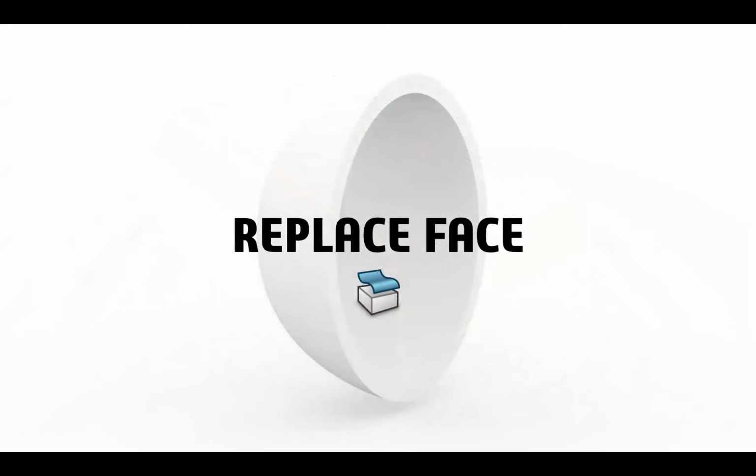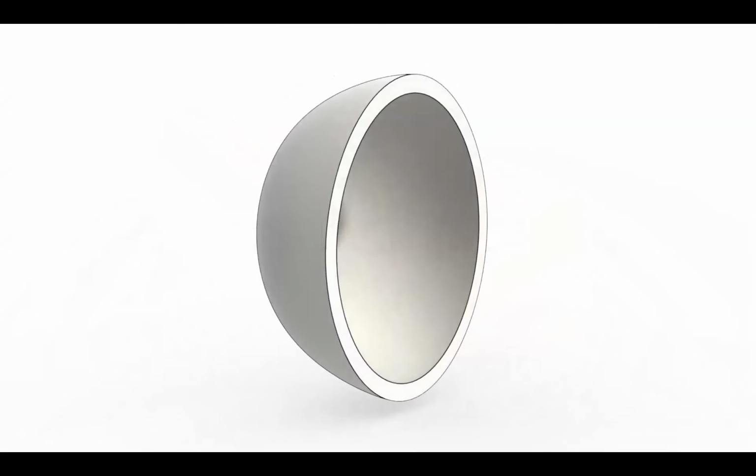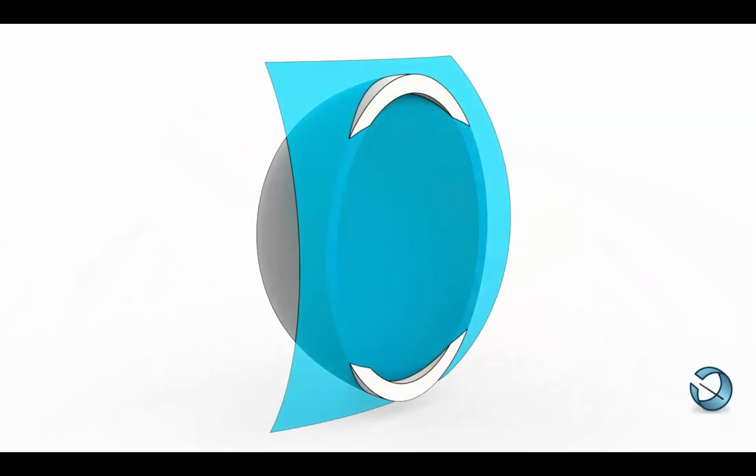Replace face is pretty cool. If you haven't used this before, you can, any part you have, make some other contoured surface and then replace the face of the part with a surface body. So, you know, got to revolve here. Pretty simple, but a flat face. But maybe I need it to be sculpted on this side. Right? Okay, well, we could revolve a little more on and then do a cut from the side. You can just do this because this way you'll avoid creating extra faces, even if it doesn't intersect completely.